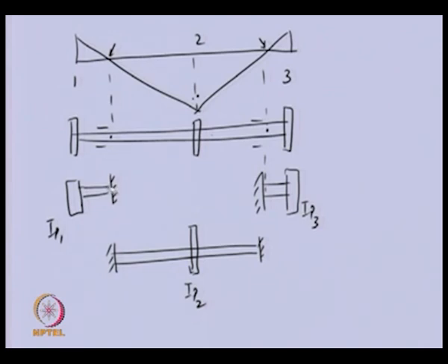So, here the main aim is to obtain these segments, these lengths of the shaft segments. If we can obtain these shaft segment lengths, then we can obtain the natural frequency of either of these systems, which all belong to the same system. So, their natural frequency should be the same as the original system. So, now we will write the natural frequency of these systems for unknown lengths of the shafts, and from there we will try to obtain the lengths of these shaft segments.